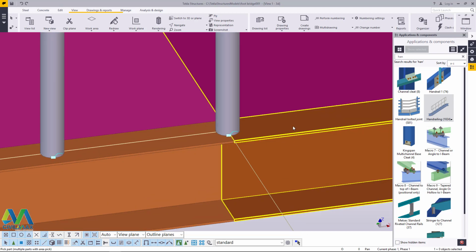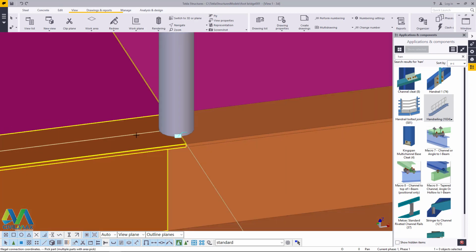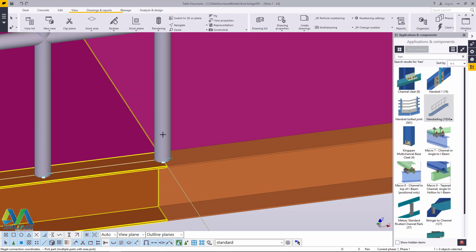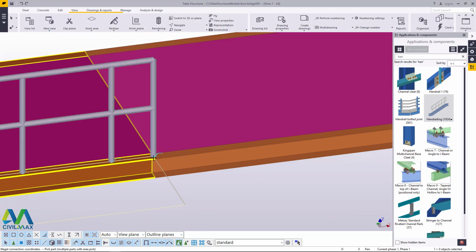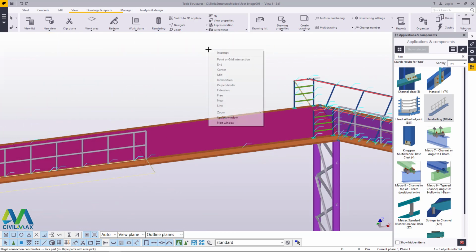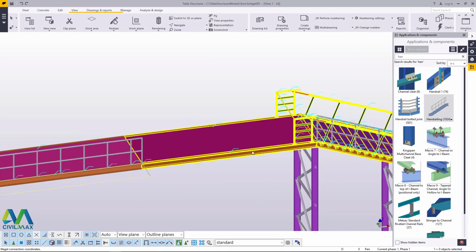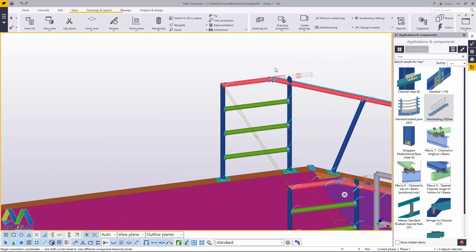I'll come back here and click that and bring this as close as possible, and I'll snap on that spot, and that has not been accepted because this is considered a handrail on this side. Now I'll come back and select that and position it on that position. It is still not accepting because everything is in assembly. So what I'll do, I'll select this and change this and remove the assembly.